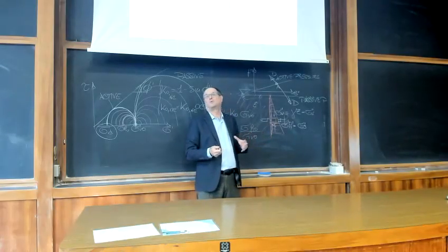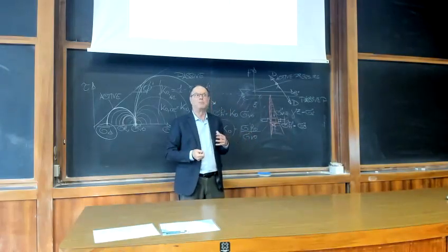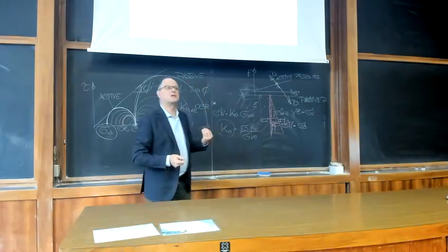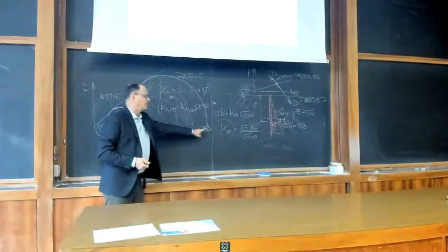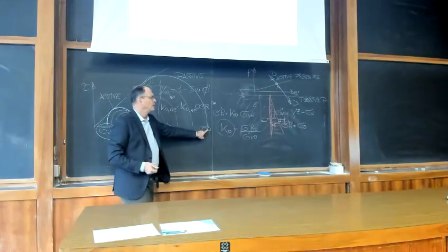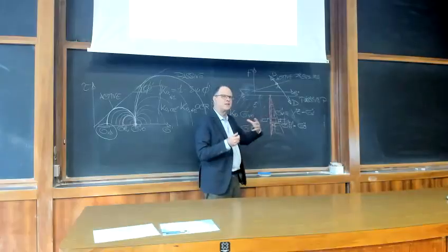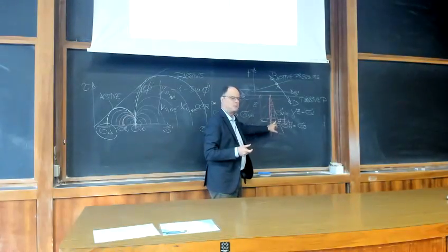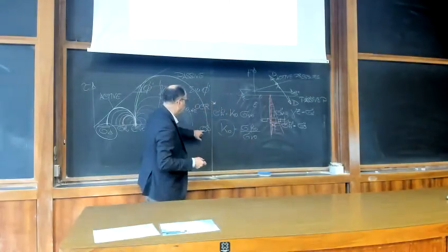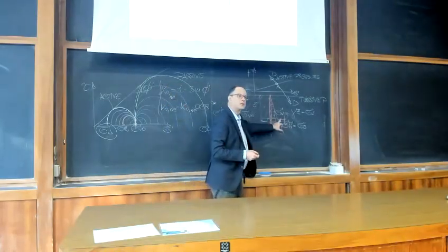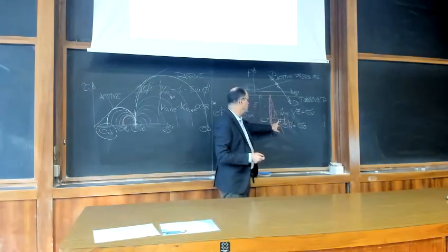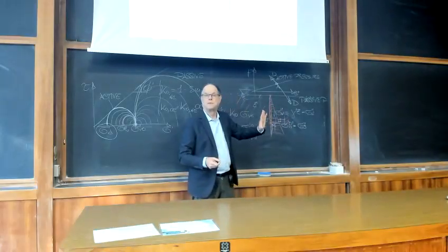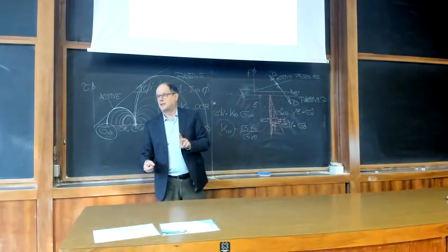You typically tend to design with the maximum possible horizontal stress. So which is the maximum? This one. So we should, in principle, if you don't understand the mechanism, you say, well, I will get the maximum horizontal stress. Because you can have a situation like that with a passive condition, and so I will say, no, I will use the passive, so I want to be conservative. Now, two things.